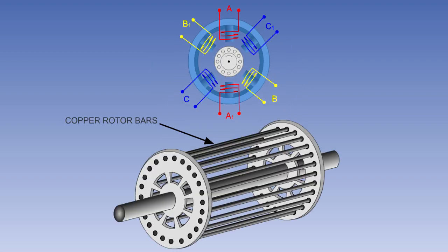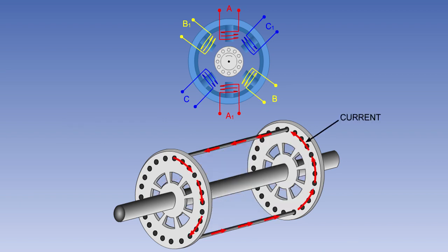The rotor usually consists of a cylindrical laminated iron core which has a number of longitudinal bars of copper evenly spaced around the circumference. These bars are joined at either end by rings of the same material to form a composite structure called, because of its shape, a squirrel cage. The rotor bars are made of very low resistance material so that a large current can flow through them. The rotating magnetic field produced in the stator cuts through the bars of the rotor, which along with the end rings form a closed circuit of low resistance.